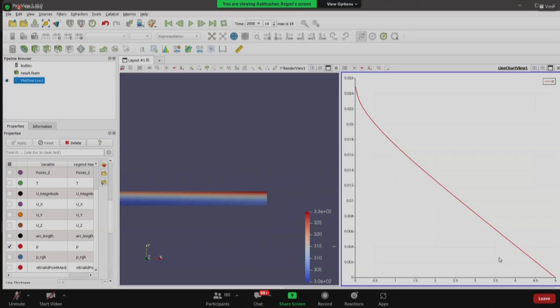And based on that, the pressure boundary condition at the inlet was given zero gradient. Based on this value of pressure, it is going to calculate the pressure at the inlet and throughout my domain, so that it will maintain that flow of 0.07 meter per second around that. So this is how you simulate convective heat transfer through a pipe.